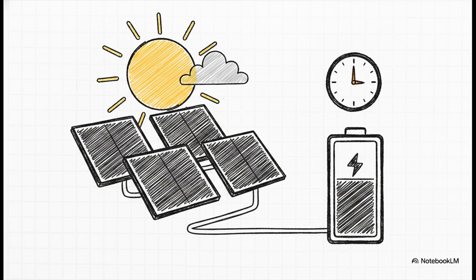Well, in the real world, solar panels typically only run at about 70% efficiency. So factoring that in, our 404-watt array will realistically output roughly 283 watts of actual power. That means recharging our lead-acid battery bank from empty to full will take just under 10 hours of solid sunlight.